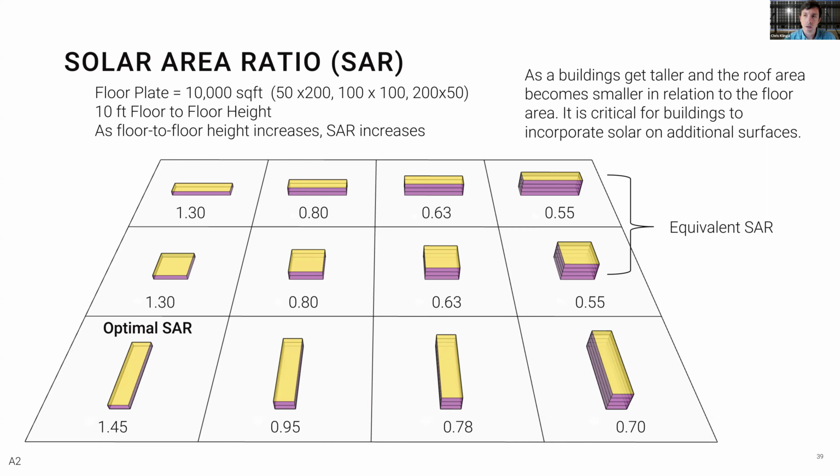Yeah, I think the other thing to keep in mind is that today there are spandrel areas that are opaque, and there are shadow boxes that increase the heat gain of buildings. And I think the real question is, if you add solar to those same assemblies, would it increase the heat gain in a big way? My general take is that it's at least reduced by what we're converting to electricity. So when you compare one to another, I think it's a negligible amount of heat gain when there are already opaque frit patterns that are doing exactly this.